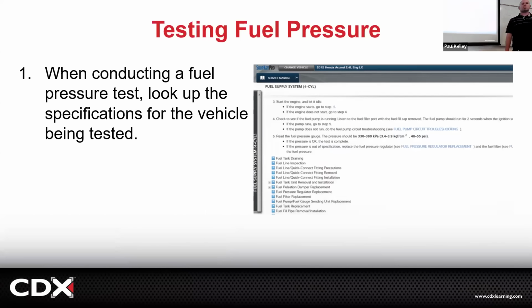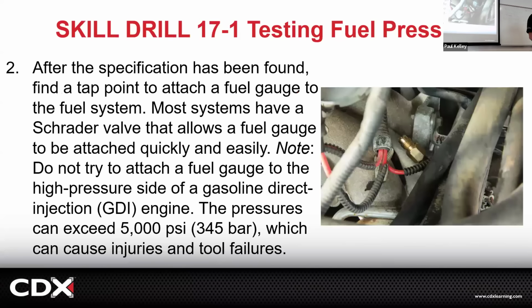Okay, let's say we're going to do a fuel pressure test. This is like a spark test. A spark test is critical. You need to do this immediately when diagnosing the car. Fuel pressure, same thing. Look up the spec. Then you have to find out where to connect it.